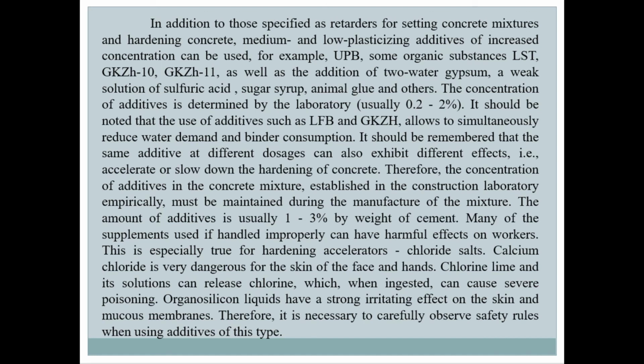Many of the additives used can have a harmful effect on workers. This is especially true for hardening accelerators, chloride salts. Calcium chloride is very dangerous for the skin of the face and hands.